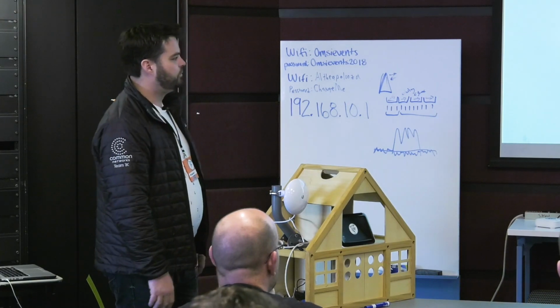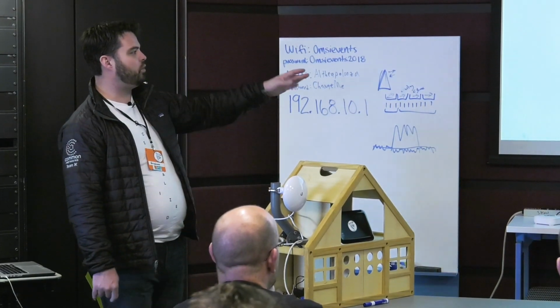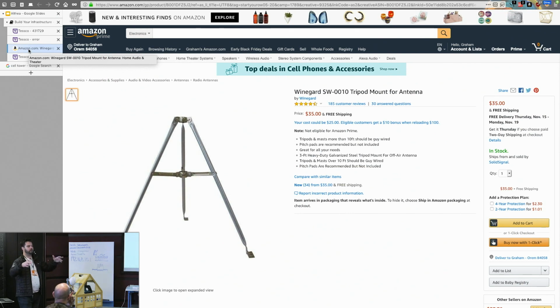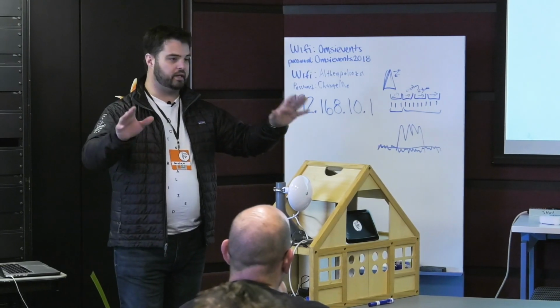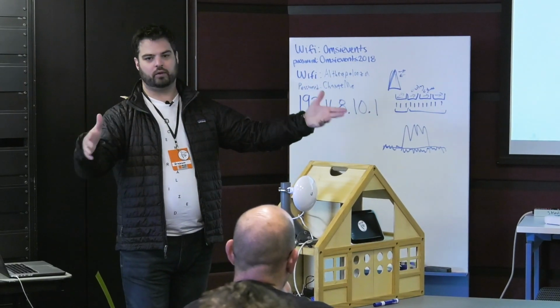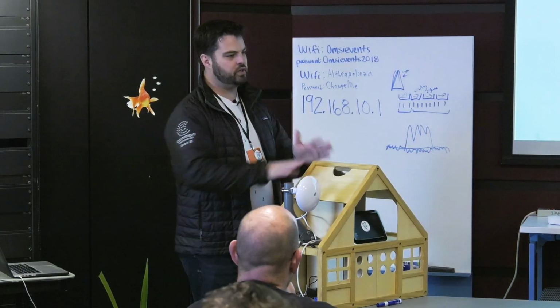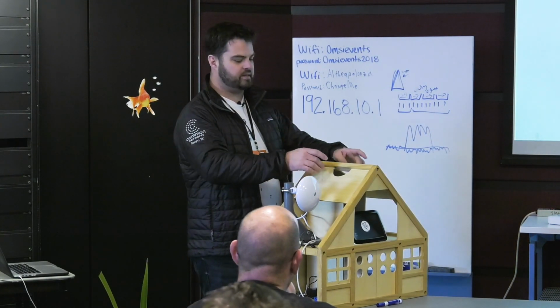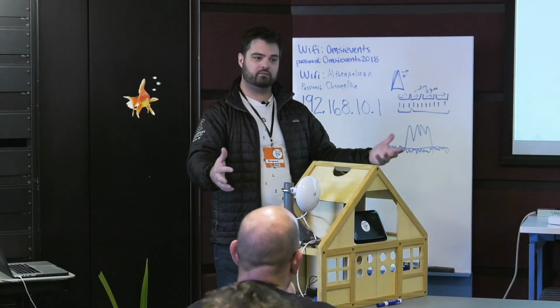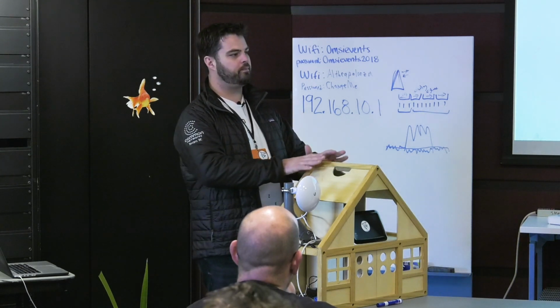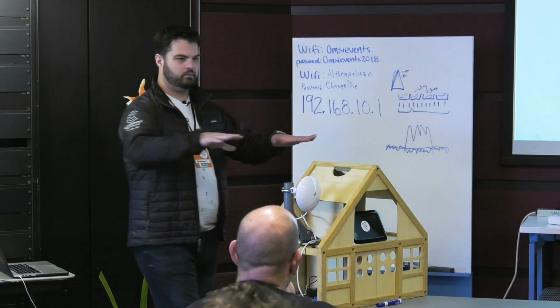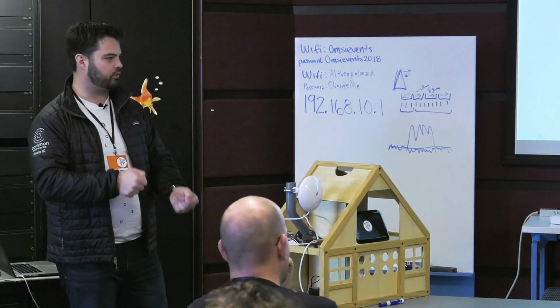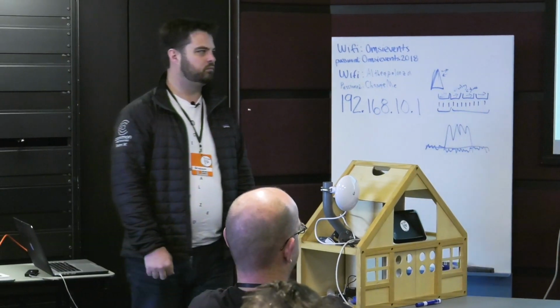But you definitely don't want to put this on a flat roof. Point of caution, you should never, ever, even if the customer says it's okay, never penetrate a flat roof. Never drill anything into the flat roof. A flat roof, water will pool on the flat roof, and they will leak at some point. If you put a hole in it, it will leak. A sloped roof, they've got shingles, the water slides off. You can seal it, and water won't penetrate because the water will slide off. The water's not pooling up. But on a flat roof, you should never, ever drill through a flat roof. Even if the customer says it's okay.